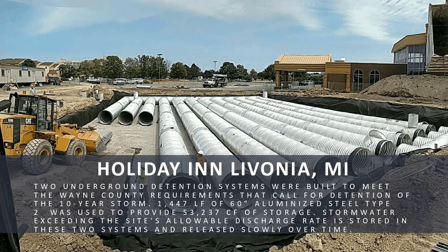And again, this is just a photo of a common corrugated steel pipe underground detention system. It includes the coupling of a number of parallel runs of pipe through common manifolds at each end of the system. The pipes are placed in close proximity to minimize the footprint and maximize the amount of storage that's available within that footprint. The pipe diameter is generally maximized to again limit the overall footprint required for the detention system. And again, you can see some of the prefabricated manifolds, some of the risers, all those features just help speed the construction and minimize the cost of the overall system.